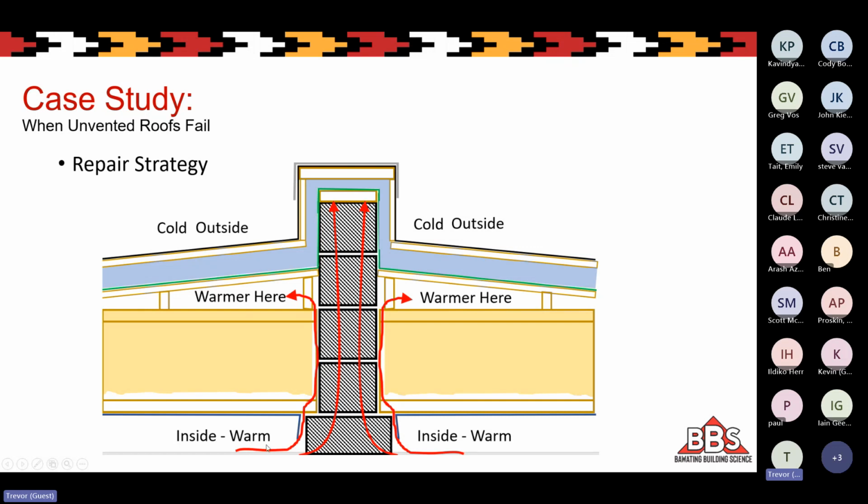And so there's still, because they didn't want to do any damage to the units from the inside, we still have air leakage probably coming into here, but because we're protected by this exterior insulation, the sheathing is no longer cold enough to have condensation, and there's no more moisture issues with this system.